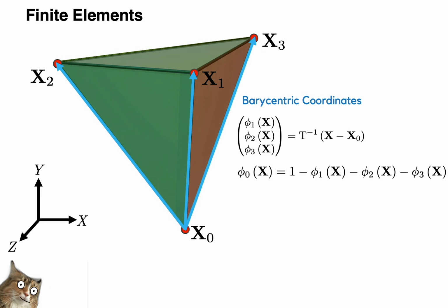These shape functions are going to take values between 0 and 1 inside our element, and by inspection we can see that they are linear in capital X. Essentially, we are saying that we will reconstruct functions inside our tetrahedron using linear interpolation. That's all well and good, but we sort of lost track of the plot here. The game, the real game, was to understand how all this works when our tetrahedron is part of a deforming object. Fortunately, we can use the tools we've just developed to sort that out.